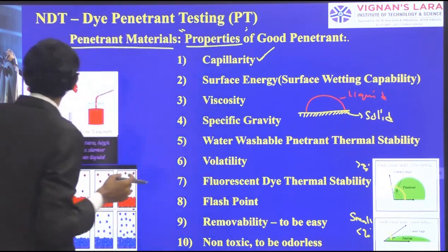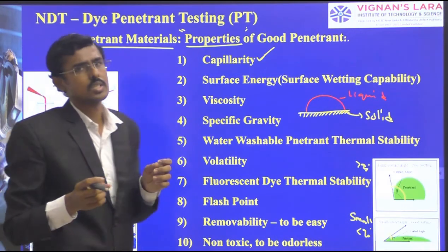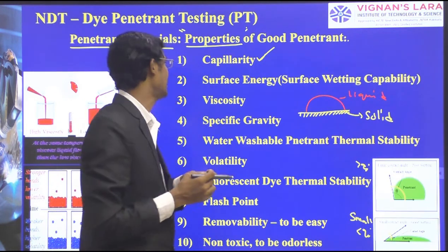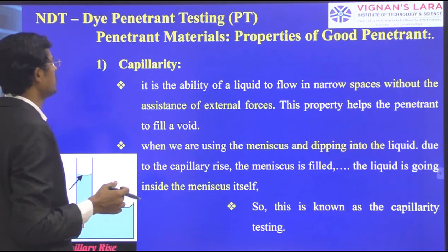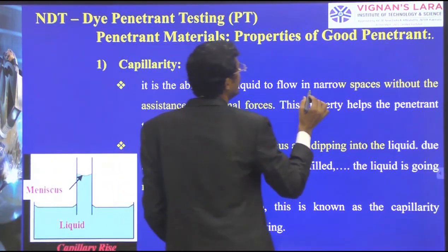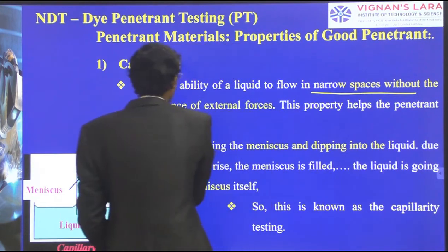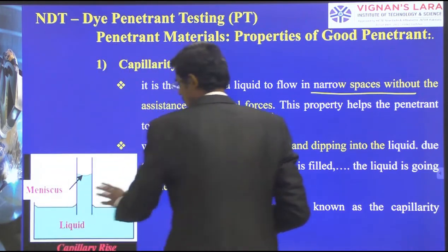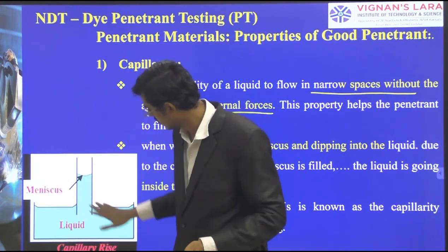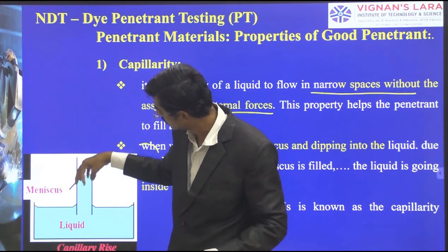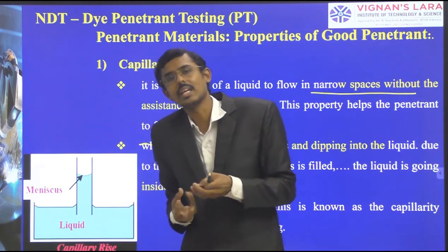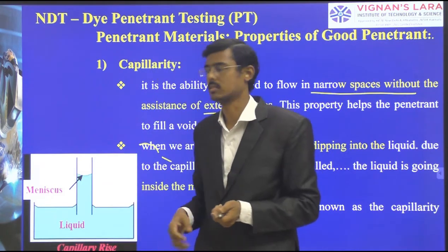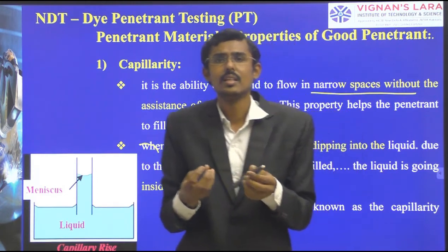Now again we come across capillary action due to these surface forces, energy, surface tension. Capillary action is nothing but the ability of the liquid to flow into a narrow space without the assistance of external force. We are not giving pressure over there. You see, this is the pipe and tube. We have a liquid at the bottom, and we are keeping the tube inside. Something happens to push automatically. We are not giving external force. It pushes the liquid in the upward direction. That happens by the capillary action.